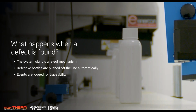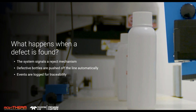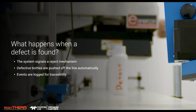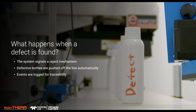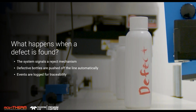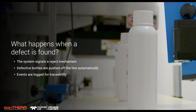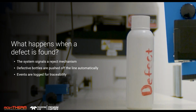In the video that you're watching right now, we have yet another method, and that's if you don't have a PLC and you want to be able to track the bottle, we put an encoder on the conveyor, and we put a small micro PLC in our enclosure. And now we track a physical distance. And once we get to that distance, we can go ahead and fire a signal to the rejector to kick it out.